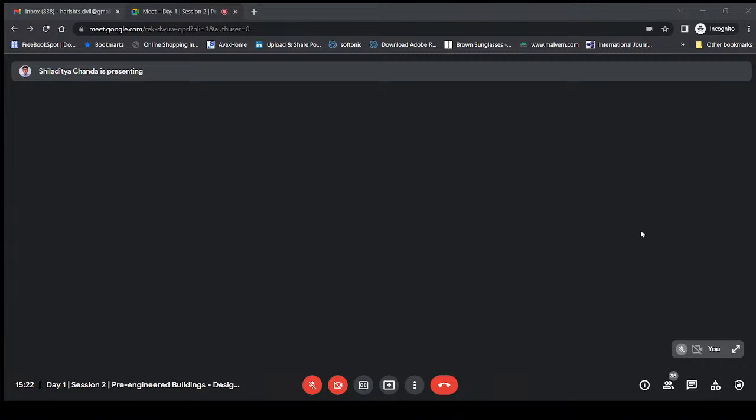Here, when the shear force is much more, you can detail your rafter like this. When the shear force is less, you can detail your rafter or column connection like this. The same thing over here, only your rafter and column connect in a sloped line. Here also the rafter connects with the column in a sloped manner. So these are 4 typical connections.